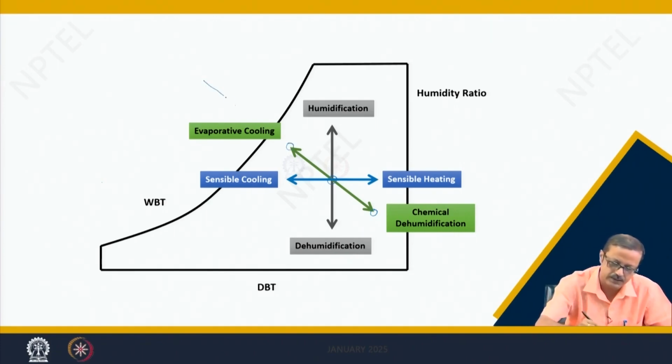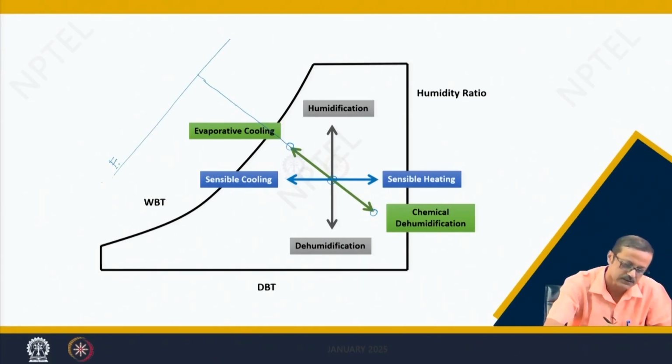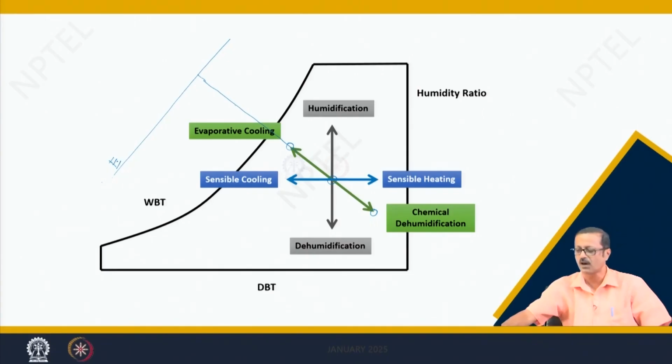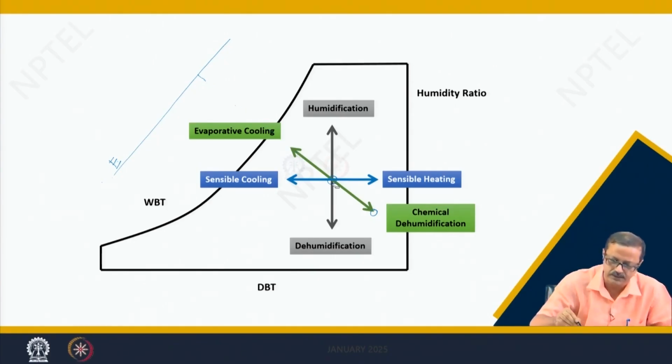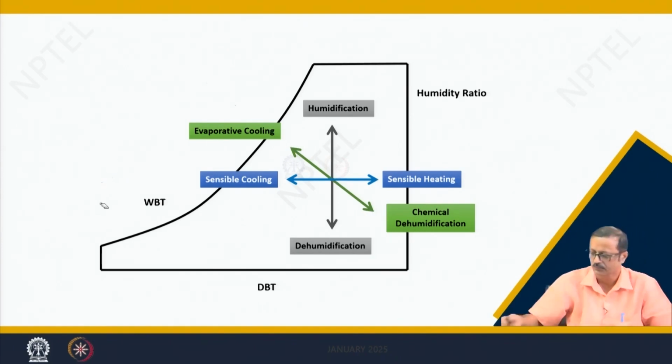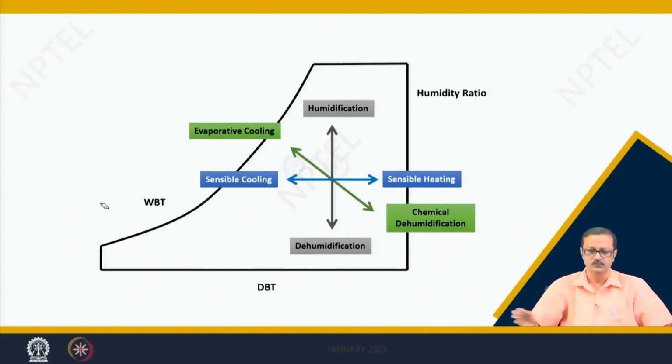So, in here, as it is parallel, it is perpendicular to the energy axis or the enthalpy axis, there will be almost no change or negligible change of the energy. So, that is one of the psychrometric advantages we can take, and we can manipulate that, and we can think of something like passive cooling systems or maybe low energy cooling systems.